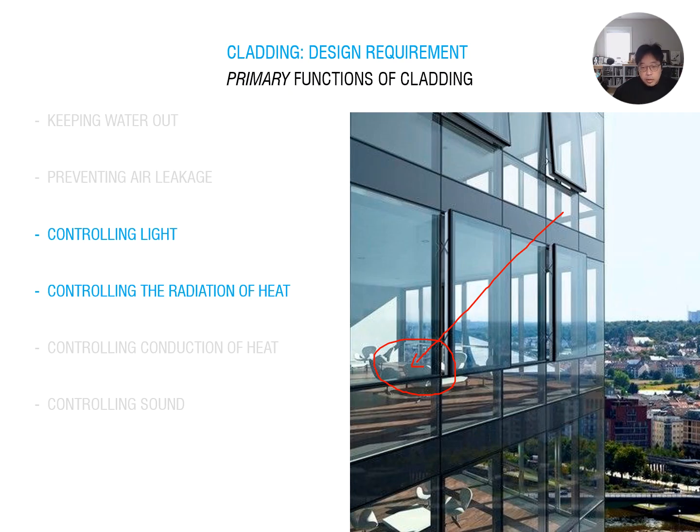You have to think about low-E coating outside, right? And double and triple glazing systems, and adding the spacer to make the vacuum space, and also injecting argon gas to increase this thermal performance value. Okay. And then also you have to consider proper glass use to control latent heat.